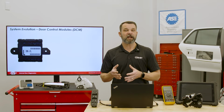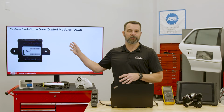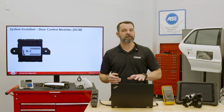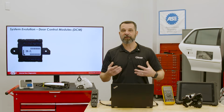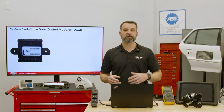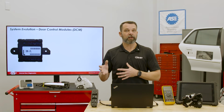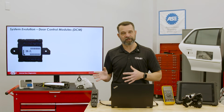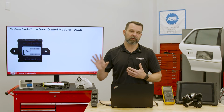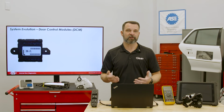today, because manufacturers have adopted and are increasing the use of yet another module, the DCM, or the door control module. And so as these vehicles have evolved, door systems have become way more complex, and they have all these new things like auto up, auto down windows, folding mirrors, lock logic, child safety lock management, all these things, right? And so instead of running 20 plus wires from every switch back to the BCM, engineers have started using the DCM to consolidate everything right at the door. Then only a power and a ground and maybe a couple of communication wires are needed.